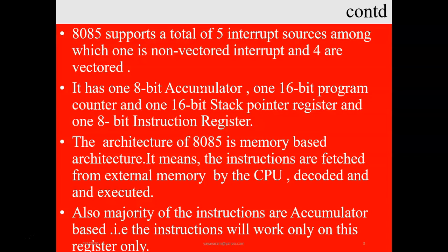These are the sources because of which the normal execution of the program, the normal execution of the microprocessor, is interrupted. We'll consider this in the next video. Next, it has one 8-bit accumulator, one 16-bit program counter, one 16-bit stack pointer register, and one 8-bit instruction register.